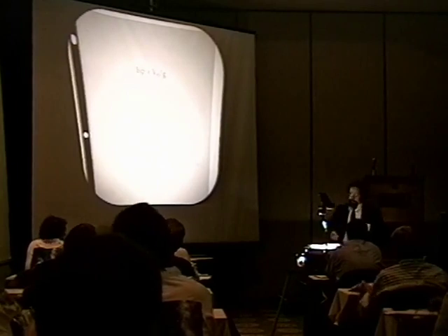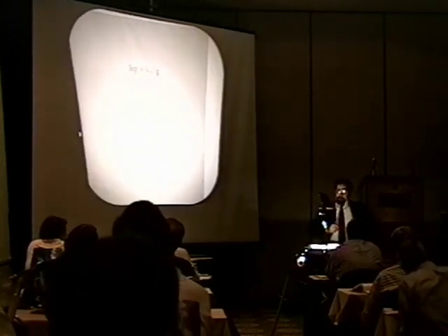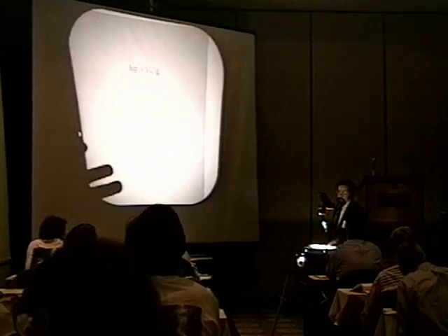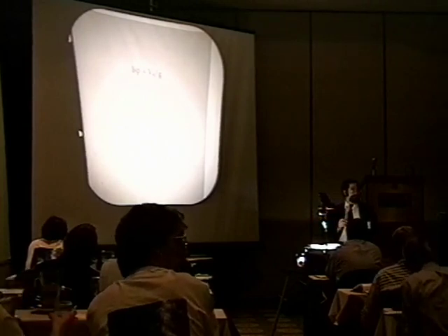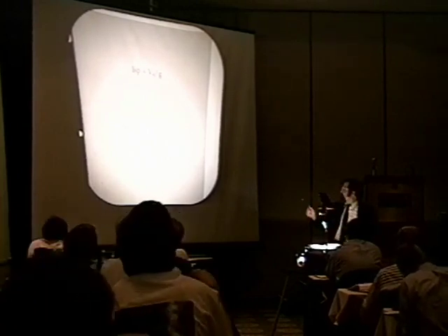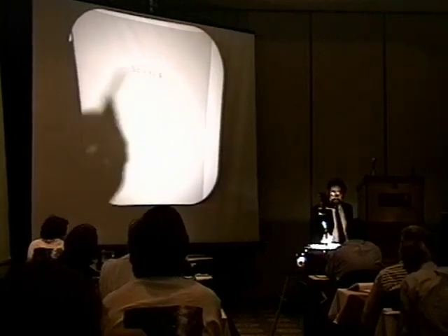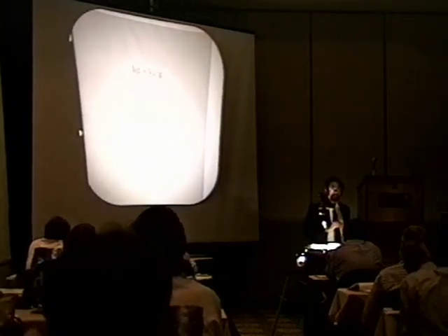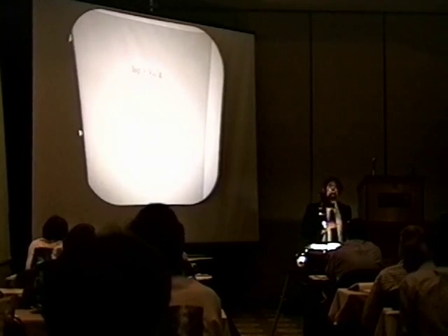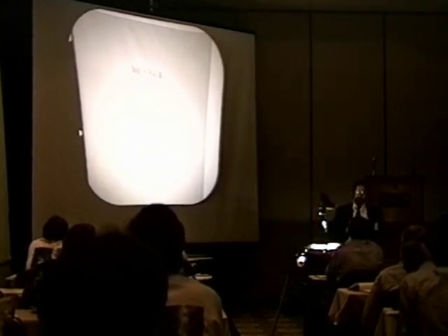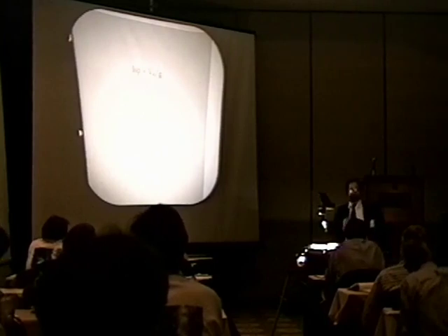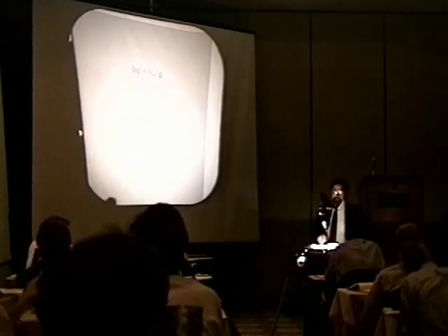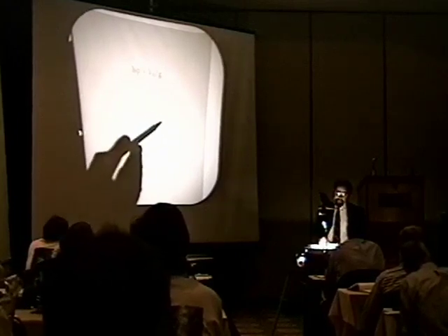For you people who are not astronautics people, which I trust are many of you, the basic parameter that characterizes a rocket engine's performance is specific impulse, Isp, or the exhaust velocity divided by the acceleration of gravity. It turns out to be in units of seconds. Chemical propellants, hydrogen and oxygen, have a specific impulse of 460 seconds. The nuclear rocket, to give an example, the solid core nuclear rocket, was tested and had an Isp of 845 seconds. And what's the advantage of high Isp?